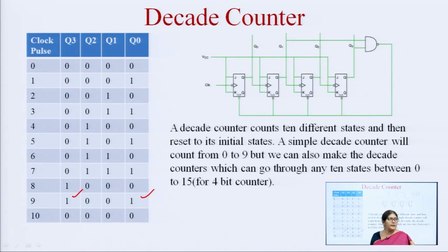Here we can see in the diagram that the first is Q1, where the clock pulse is applied, and this is a synchronous counter. The output of this flip flop and the output of the other flip flop, for 1 0 0 1, are connected through this AND, and its output is connected here.